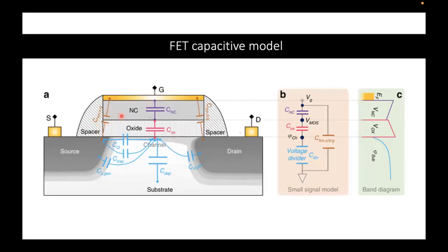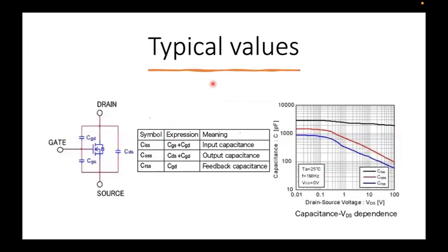And as we previously discussed, there is an overlapping area between this oxide and the source, making this orange capacitance, if you remember. 2 lectures ago, we already demonstrated. So simply, this is a capacitance connecting the gate to the source. So we can call it here, as you can see, CGS, or the capacitance from gate to source, and so on.